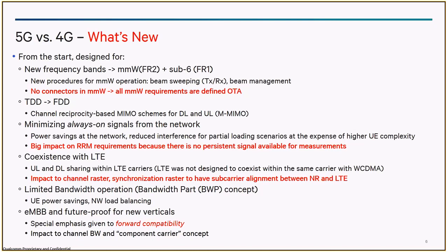Now by splitting this into chunks, I can have some RACH slots in this 5 megahertz, some more RACH slots in this, where for this 5 megahertz, only the mobiles assigned to that slot will be able to access, not the other ones, right? Somehow that load balancing can happen from the uplink side. Of course, maybe only for the initial access. That is one kind of load balancing, but there could be multiple others.